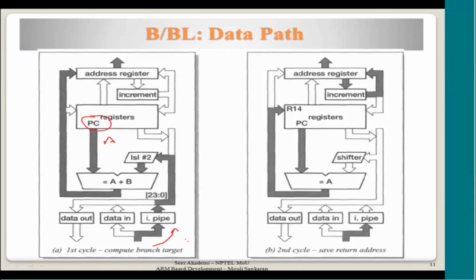Why should it come from here? It is not sitting anywhere in a register. Please remember, the offset was with the instruction which was fetched and decoded, and then passed through a pipeline register. Between the stages there are pipeline registers which carry the information about that particular instruction. So it passes on the offset value read from the instruction, coming through this backdoor entry.